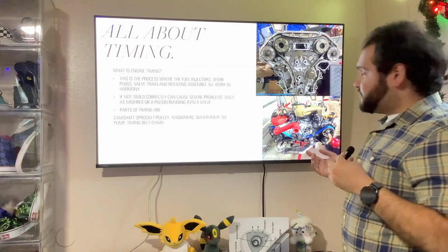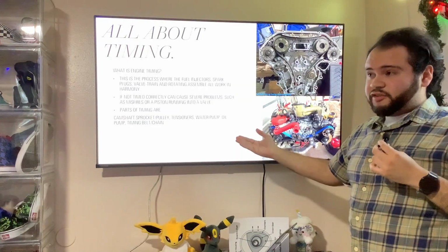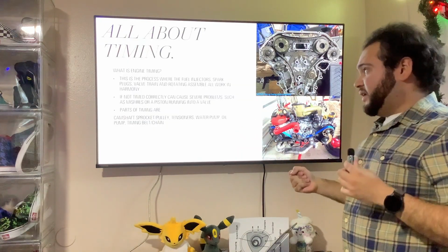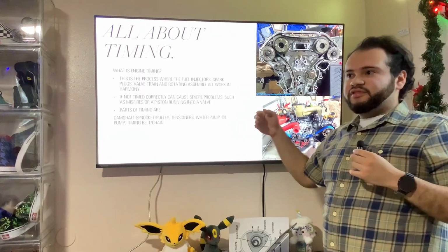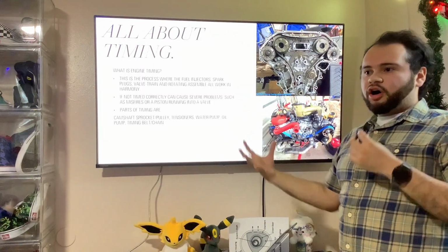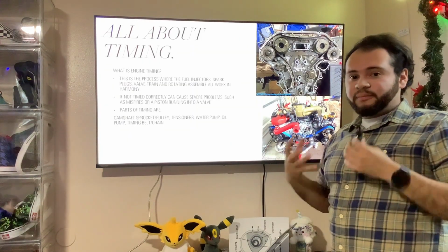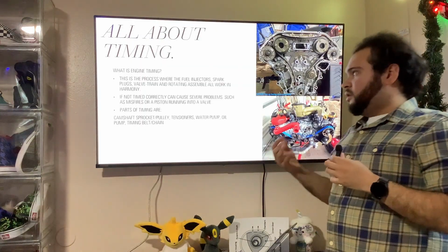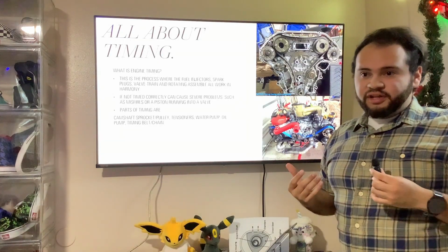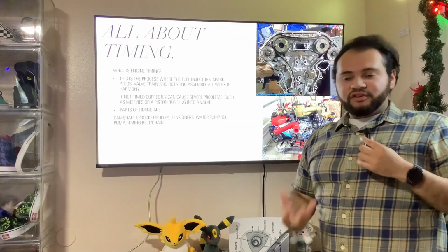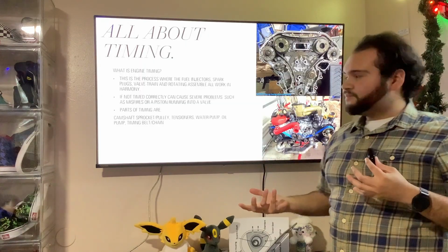It's all about timing. And while we have talked about the four-stroke process, that won't be possible without timing. What is timing? Timing is the process where the fuel injectors, your spark plugs, your pistons, valves, and rods are all working in harmony to create power, and they're not getting in each other's way. They're all working as a perfect unified team. Without timing, you would have misfires, you wouldn't be making the power you need, your car would be running dirtier, and you could have a piston hit the valve and basically destroy your motor.